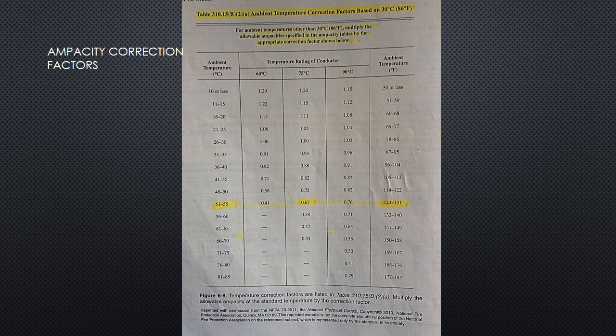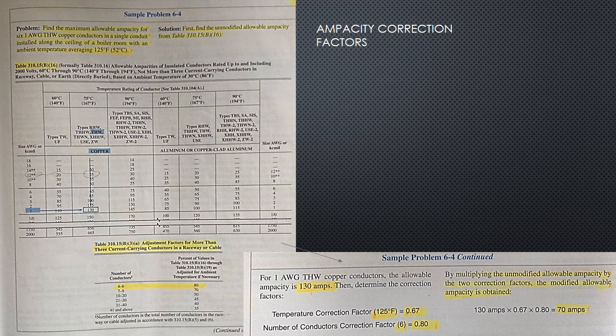The ampacities of different conductor types vary differently with temperature change. Therefore, each type of conductor has unique temperature corrections. As the ambient temperature increases, the ampacity of the conductor is reduced. Conductors installed close together as in a raceway are exposed to heat generated by the surrounding cables. This heat is not readily dissipated because the air in the conduit is fairly still.